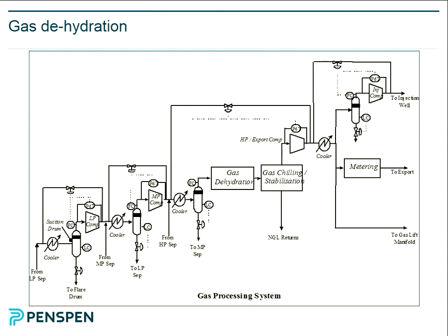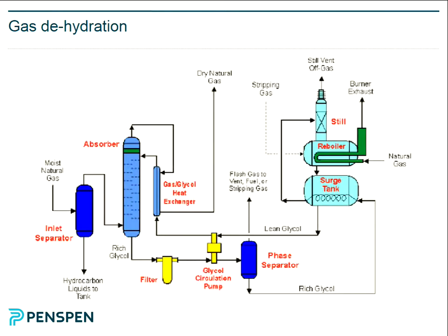There's a similar way of removing CO2. Same thing: you've got an H2S or CO2 absorber, using a solvent. Amine is one of the solvents they use. So you've got feed gas coming in, and they use the absorber, and you circulate the solvent and clean it up.